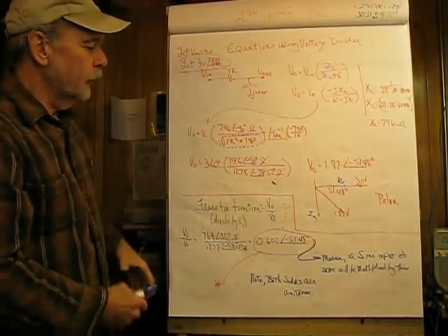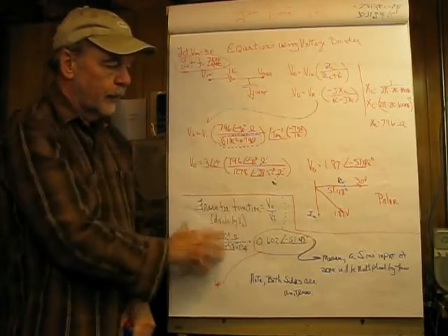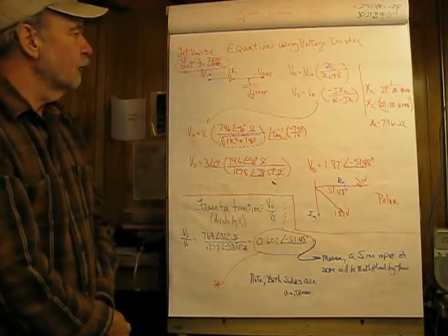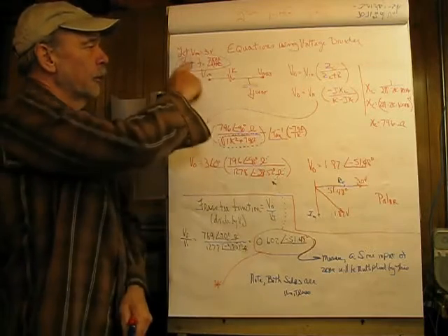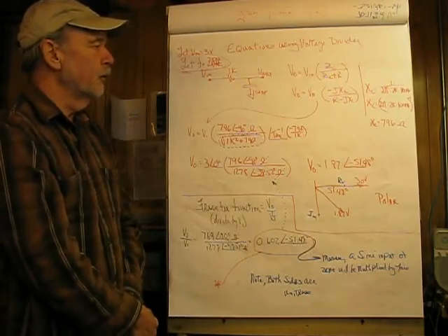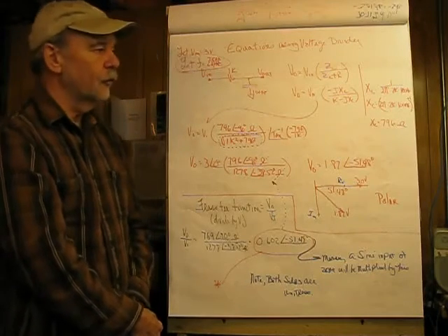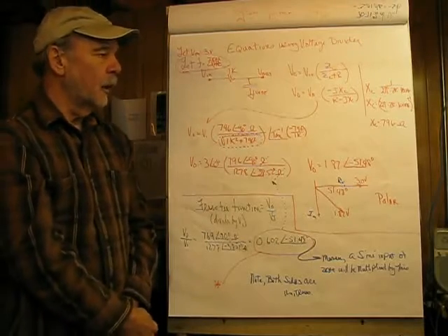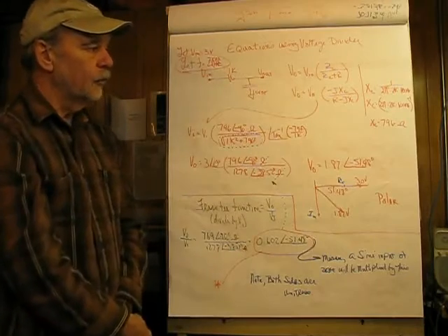Okay, let's do some calculations here, and what we're setting up for is a different method of solving this, very similar, but just as a refresher, we're going to use voltage divider to do this. I'm going to let my input voltage be 3 volts, and I'm going to let my frequency of interest be 2 kilohertz in this case, and we have the same circuit values we had before, 1K and 100 nanofarad, V in and V out labeled as such.